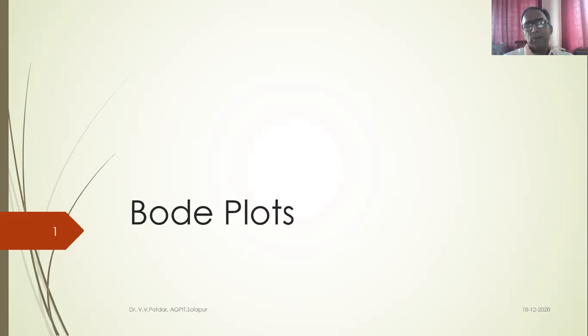Displacement x, isn't it? For a linearly increasing force function, how is the displacement varying? As I solve this differential equation, this transfer function, whatever displacement I get, I try to find out whether it is within the permissible limit or not. If it is not, I keep on changing. On the right hand side of my transfer function, what is there? 1 upon m D square plus bD plus k. Now what are the variables? Mass can be varied, damping factor b can be varied, k can be varied.